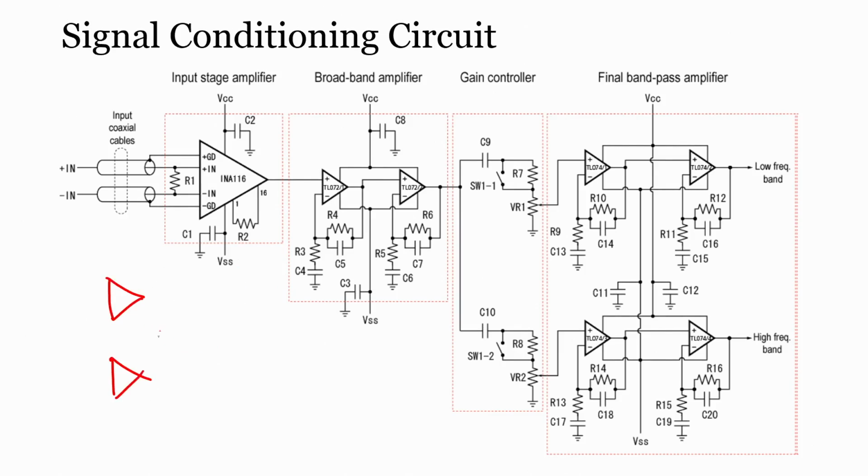1, 2, a resistor in between. This is minus, this is plus, this is IN minus, this is IN plus. Since we always require negative feedback, this will be connected at this point, whereas this will be connected at this point. This acts as the gain, whereas the third operational amplifier is in differential amplifier configuration with a gain of 1.